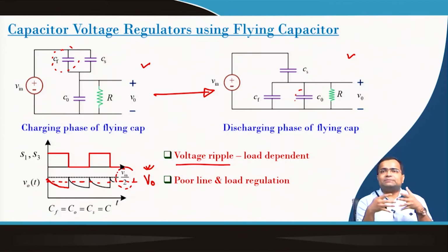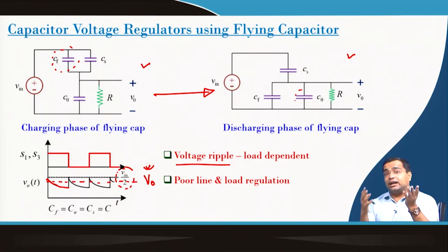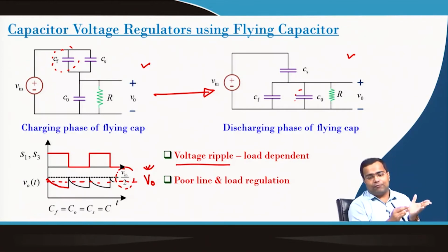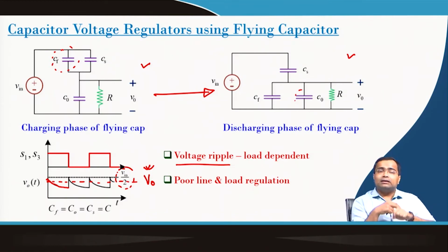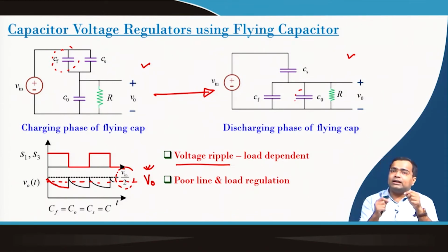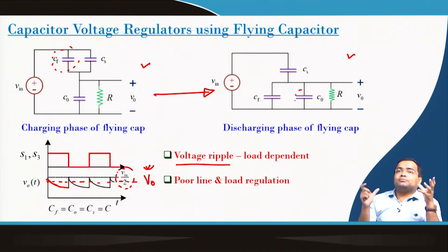So, this voltage mismatch will cause a huge inrush current. That means a huge inrush current will go from the flying capacitor to the output capacitor, and it is important to limit the current. So, we also want to make sure that very large voltage variation is not desirable, and the amount of current also depends on the size of the output capacitor.